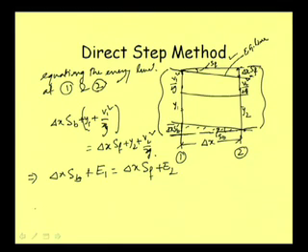Well, now from that, our target is to find out what the delta x is when y2 is the depth here and y1 is the depth here at upstream. So, knowing y1, suppose we want to know what is y2, then we know at what distance this y2 will be. So, that way we are trying to derive one relationship for this distance in terms of the known parameters at upstream and downstream. So, let us write it as delta x.